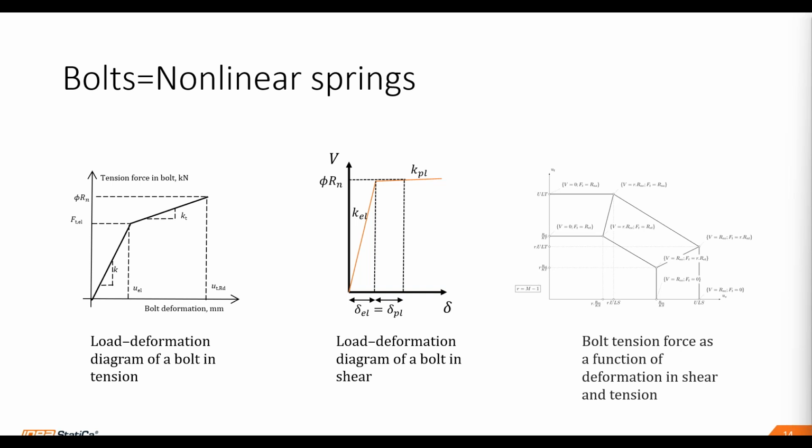And then, here you will see also the load deformation diagram of a bolt in tension, in shear, and how that bolt force is a function of deformation in shear and tension. So again, if you want more information about the formulas that we are using to calculate these values, those are in our support center in the theoretical background. But the main objective of this slide is to show you that we use nonlinear springs. All right.